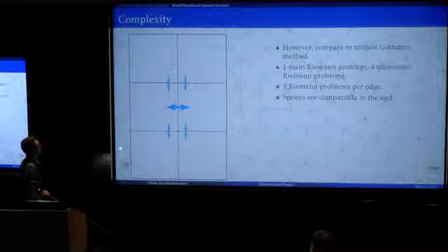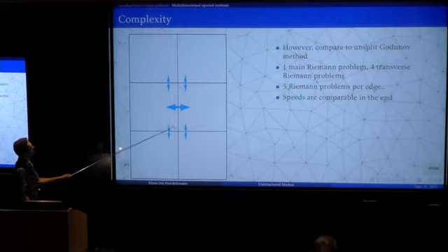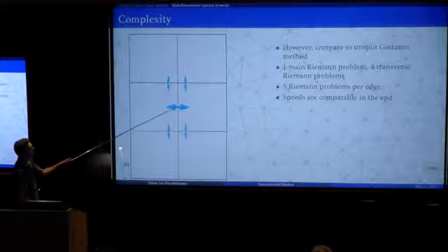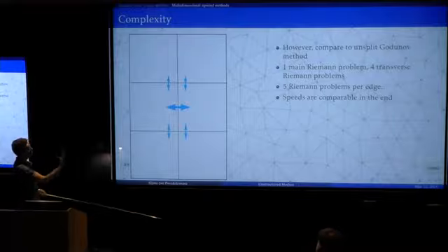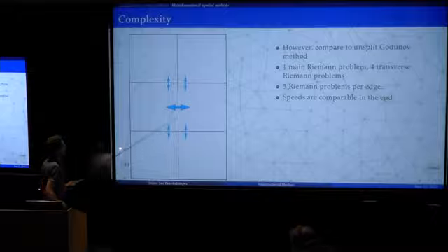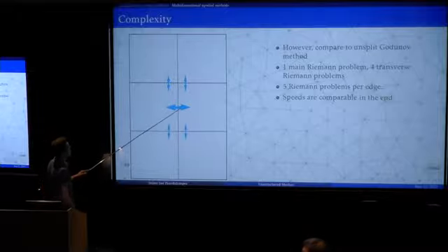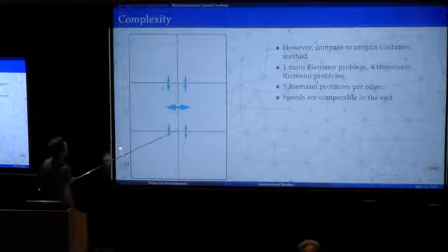But if you compare that to what you have to do for a normal rectangular grid with a Riemann solver, if you consider the interaction between these two cells, what you first of all have to do is solve a Riemann problem between the two. But then you go into the multidimensional integration. So you say, this Riemann problem, we have to solve 4 transverse Riemann problems as well, because the flow might be in this direction, for example.